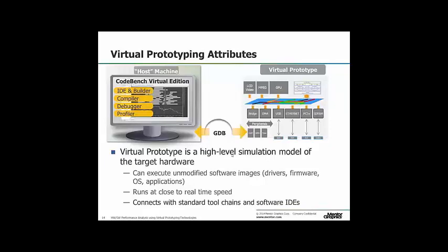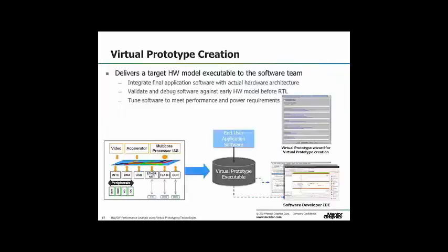So typically within a TLM platform tool, it's possible to generate this virtual prototype. You can normally generate either a Windows or a Linux-based virtual prototype depending on what the software team is using in terms of their tool set. The actual prototype should execute in the same manner as a TLM platform, but because it is just a virtual prototype, the architecture of that prototype cannot be changed. It's a static architecture. So there's normally some kind of GUI within the TLM platform tool to help produce one of these virtual prototypes.